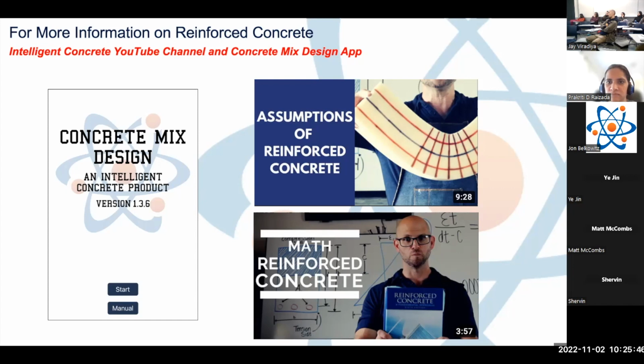And what that tells us is the bottom of the beam is in compression, or excuse me, the top of the beam is in compression, the bottom of the beam is in tension. The bottom of the beam, the steel, takes on our tension load. The top of the beam takes on our compression load.